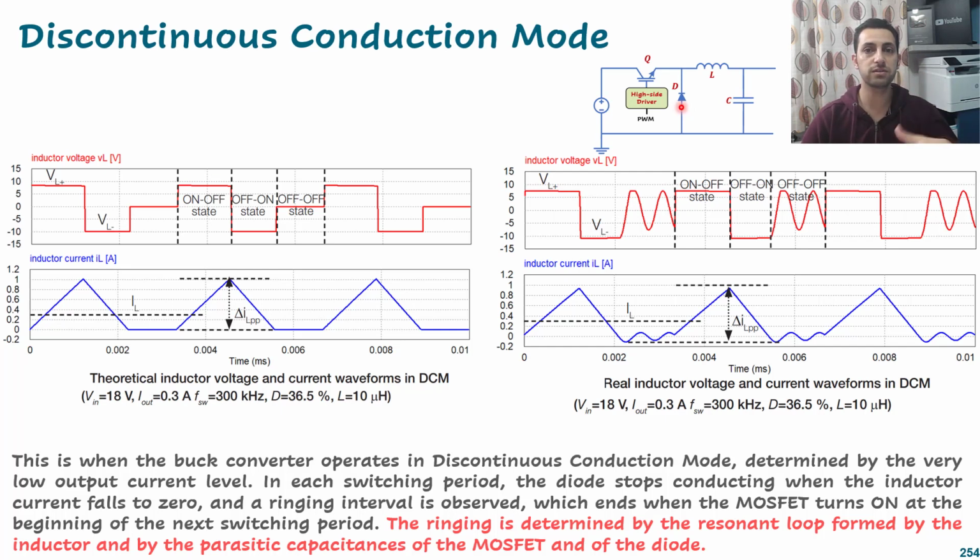All that together will produce an inductance in series or in parallel with some capacitance, and this will produce resonance like this. So we don't have a steady zero voltage here, but we have some resonating voltage, and this always appears in our circuit. If you find your circuit has oscillating current or oscillating voltage around zero here, that means you are now running in discontinuous conduction mode.